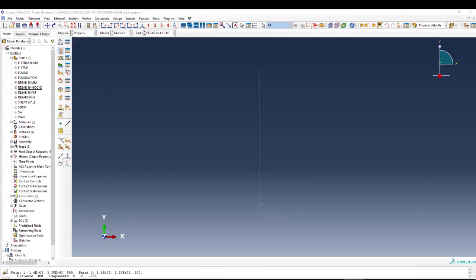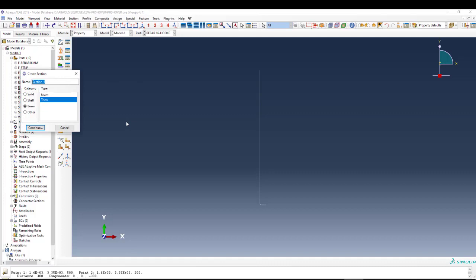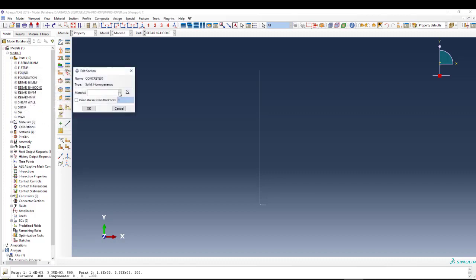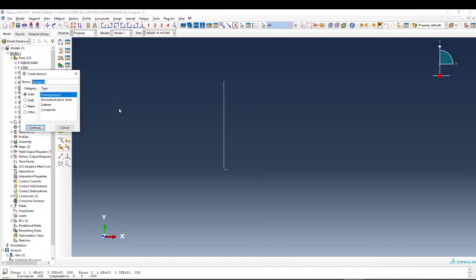So before, we have to use a solid, we can call concrete. So foundation and shear wall both have solid elements. We take solid elements which already exist. We can call concrete 30 megapascal. So we have frame concrete here, and then we can call rebar, and I'm going to show you that both elements you can use.